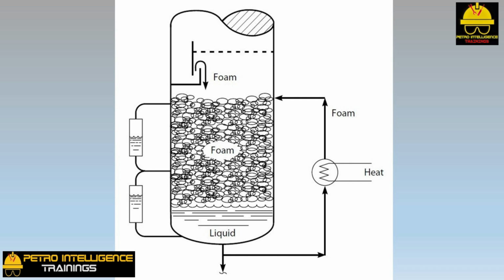If the foam is spanning both taps on a gauge glass, then the height of the liquid in the glass is a measure of the specific gravity or density of the foam in terms of the specific gravity of the liquid in the glass. If the foam is above the top tap of both the gauge glasses in this picture, then there will be a level in both glasses. The upper gauge glass will show a lower level because the light foam in the tower floats on the top of the heavier foam. Note that these split liquid levels, so often seen in a process vessel, tell us nothing about the real liquid level in the vessel. They are a sign of foam.